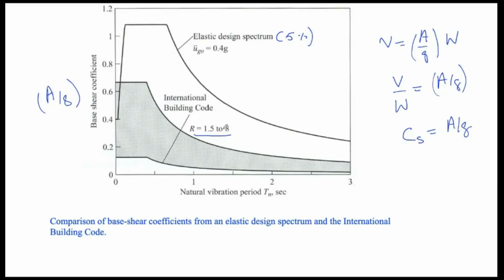But if you look at a very high value, for example 8, you can see that the base shear coefficient is very, very small. It may be something like 0.08 or 0.1, or like 0.155, 0.15 and so on, and up to, let's say, 0.7, 0.65 W for structures which are less ductile. But in any case, if you compare these values over a range of vibration periods, you will see that the elastic spectral accelerations are quite a lot larger than these base shear coefficient values.